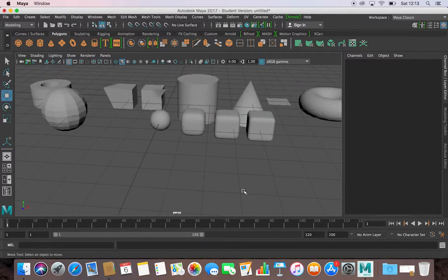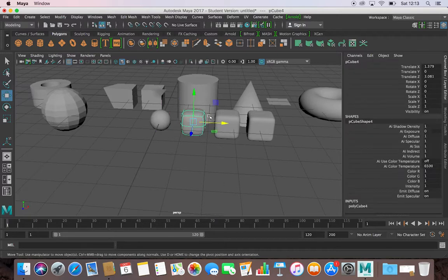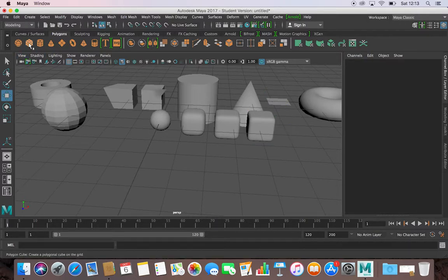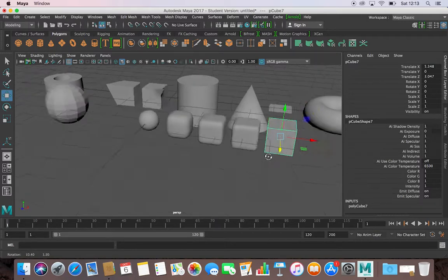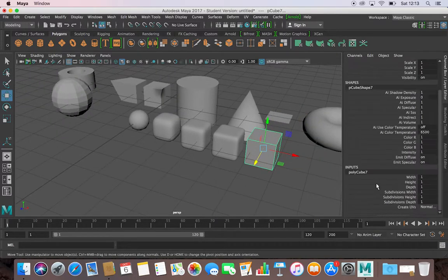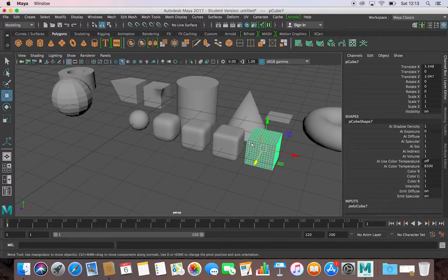So that's because we've added enough subdivision data in there for it to not smooth it over into an entire ball. And if you were doing it in this method, you would probably say that I might need to get up to, let's say, if we wanted it to basically be cube shaped, but with an ever so slight edge to it, so it's not a perfect razor edge on the end, you're probably going to want to subdivide this to something like maybe 12. So if we were to put this as 12, 12, and 12, that's going to give us that.